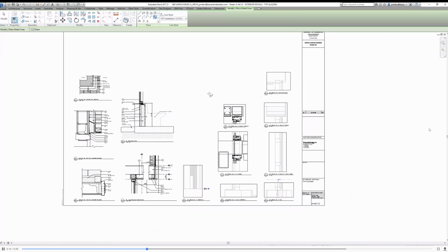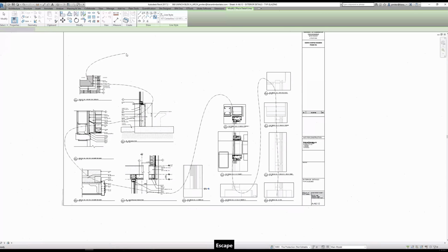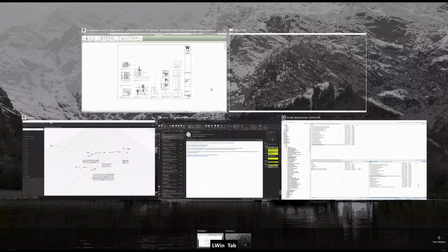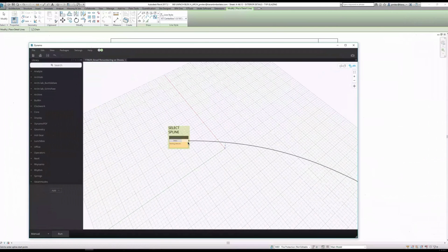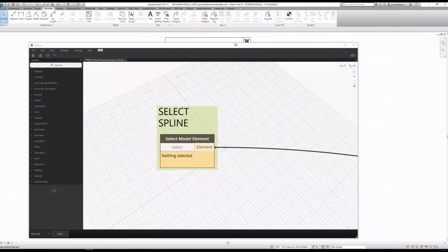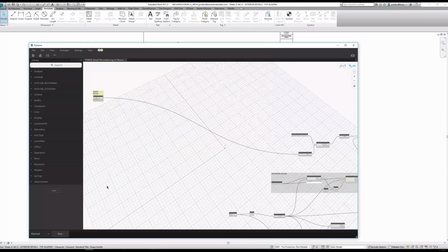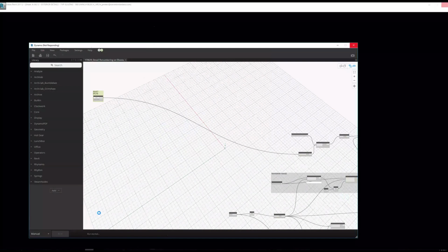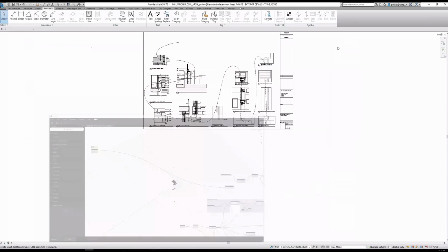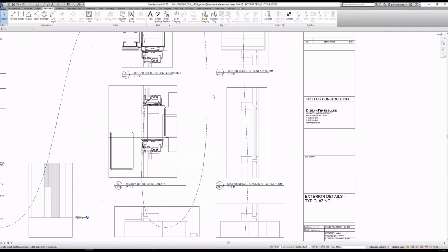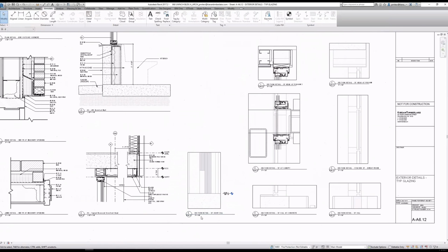those of you that have put together some drawing sheets, especially in Revit, you know that when you need to add drawings, remove drawings, or just reconfigure the sheet, it can get very annoying very quickly, because as soon as you try to change the number of a single detail, Revit says, no, you can't do that. You have another detail on the sheet with that number already. And you say, okay, well, all right, I'll change that one to 2x, and then I'll change mine to 3, and then I'll change that one back to 1, and then I'll change mine back to 2. And that's really annoying. Besides being annoying, it just wastes a ton of your time.